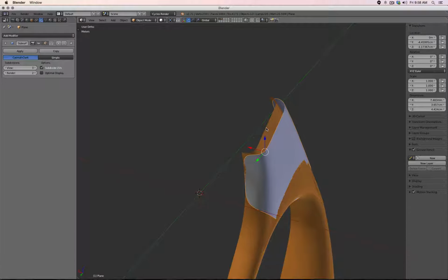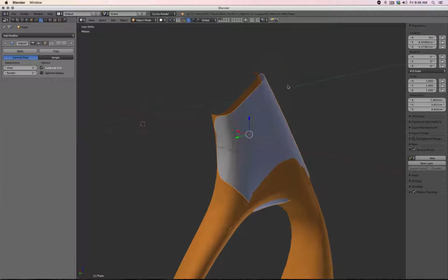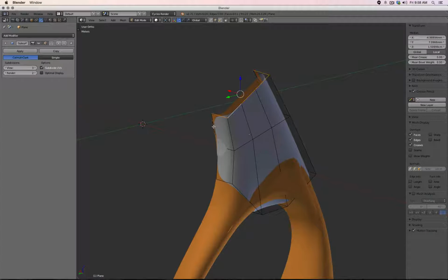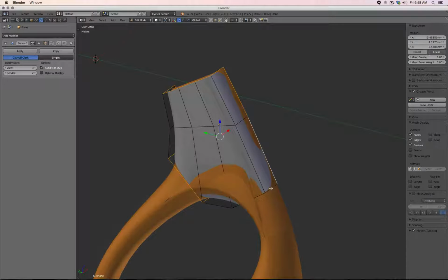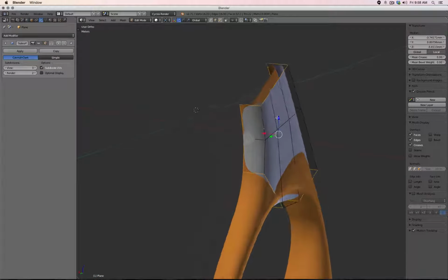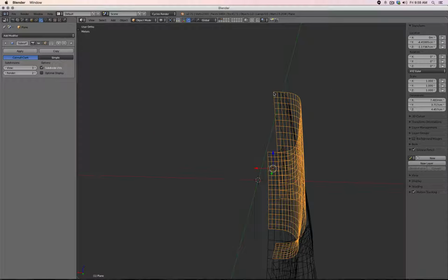We do not match our design yet, because you can see here this one is too big. But before I continue, I'm going to straighten some edges. So I select this shell, Alt click onto this edge, Shift Alt, left mouse button, Shift and then left mouse button onto each edge. And those edges I would like to crease. So here's a crease function in the property panels inside transform. You see this pushes it down. So I sharpened the corners.